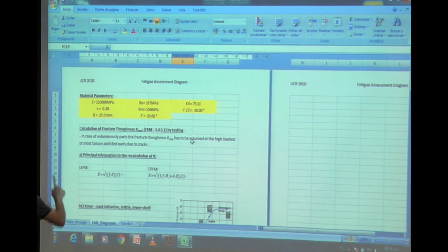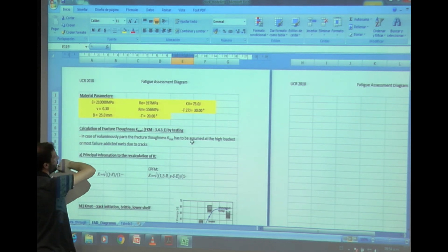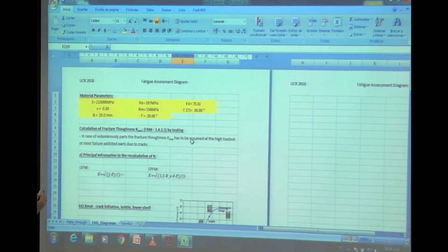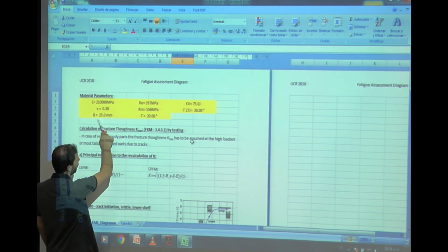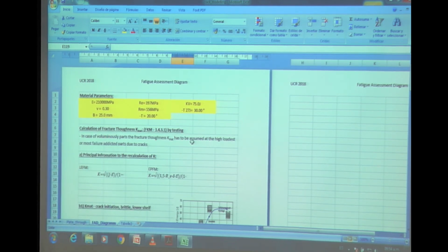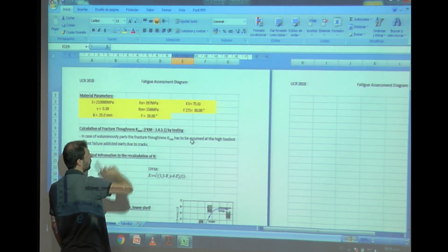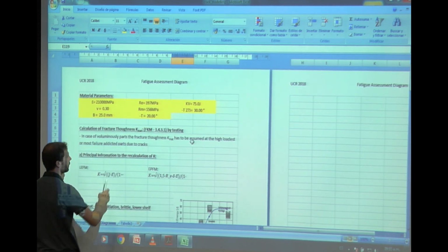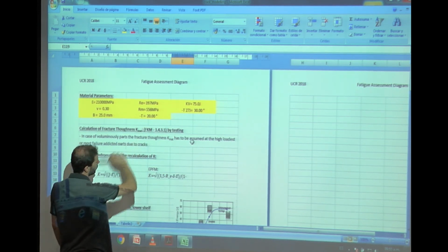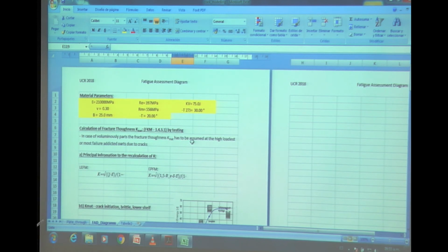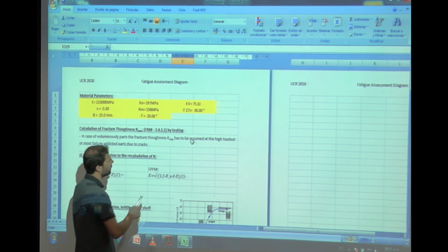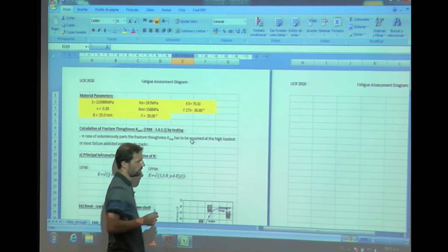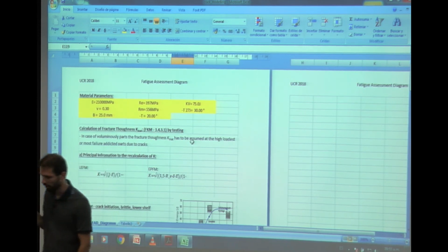Of course, here I just have the modulus of elasticity to describe the model, also the Poisson ratio. Then in this case the width for the crack through model. And here basically the information out of our tension test. This is the surface temperature, so I set here 20 degrees. And in this case, I also used the estimation of